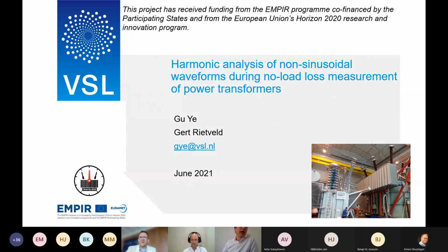Welcome to my presentation. In these 15 minutes, I would like to discuss the harmonic analysis during the no load loss measurement of power transformers. As we all know, when we perform the no load loss measurement of power transformers, we open circuit one side of the transformer. If the applied voltage is up to a certain value, the core of the transformer might be saturated, which will lead to a significant harmonic distortion. In this study, we would like to investigate the impact of this harmonic distortion on the final measured power loss.